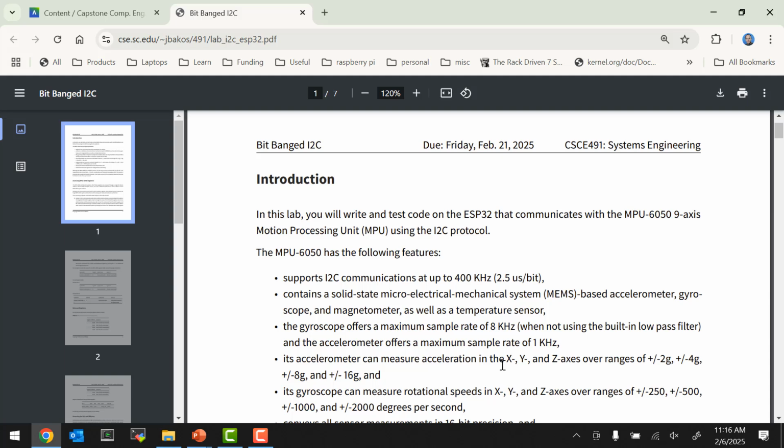So the accelerometer, we're going to try to use that to measure tilt. What we want to do is measure the force of gravity, which is going to be distributed along 3 axes, x, y, z, depending on the tilt of the sensor, right? If you have it flat, level with respect to the floor, then you'll see just acceleration in one axis, the z-axis.